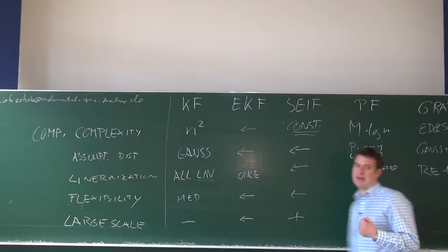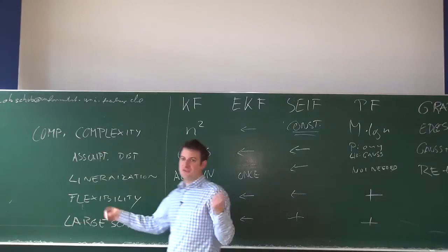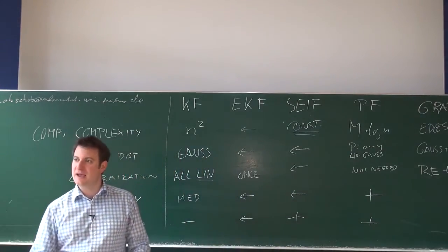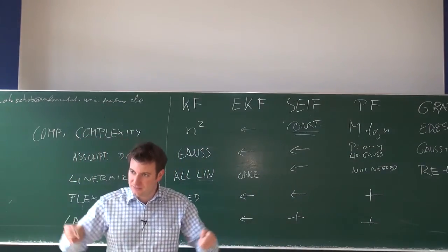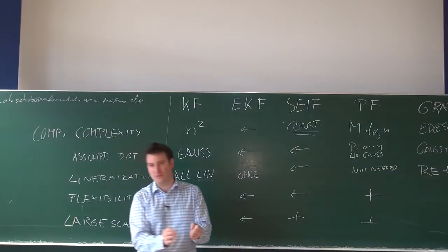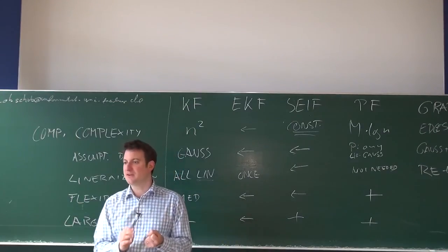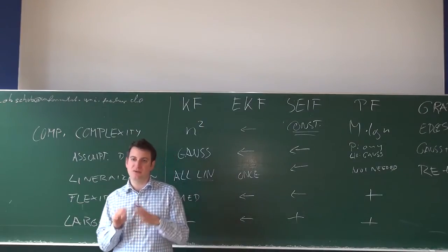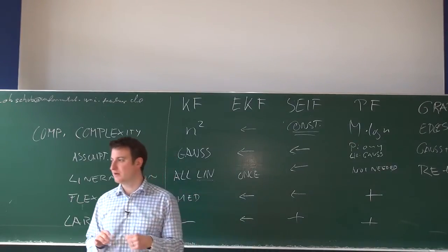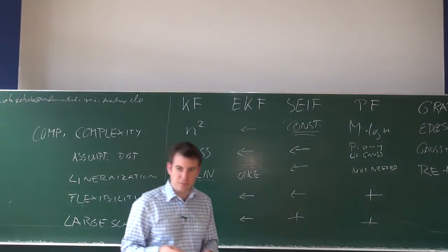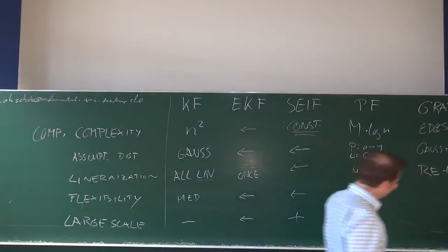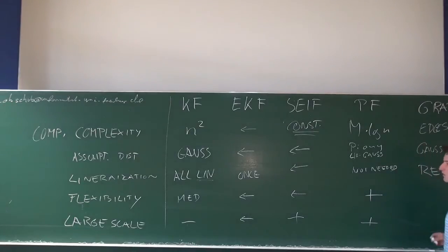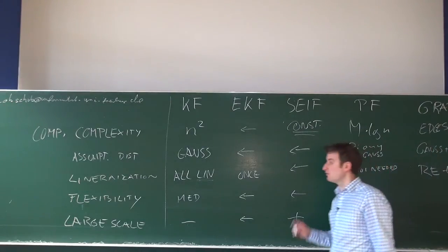And this is a big plus because even when we started with a bad solution, as we relinearize in every iteration, the closer we get to the hopefully right solution, the better the linearization gets. And that's one of the key big advantages if you deal with somewhat nonlinear systems. It's really an important point, which increases robustness dramatically, especially for large-scale mapping with the graph-based approaches.